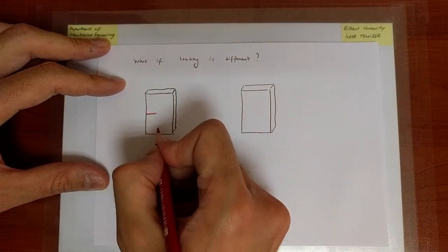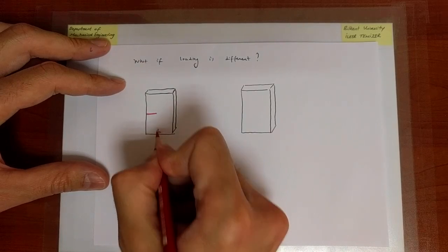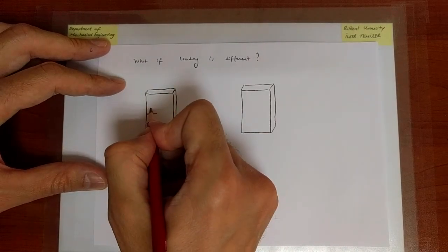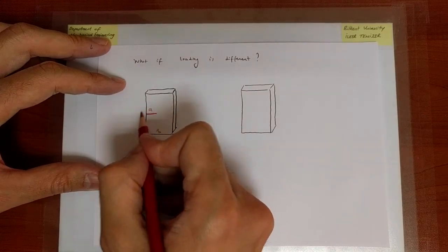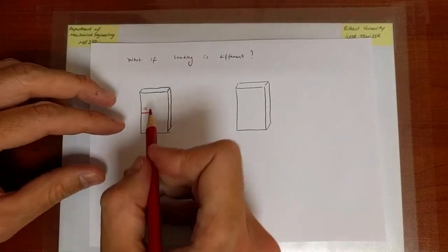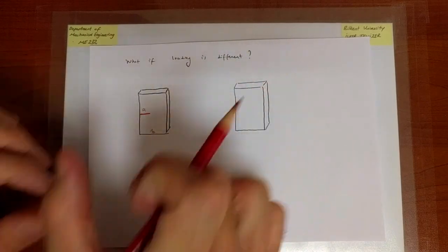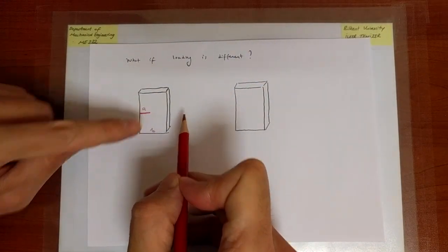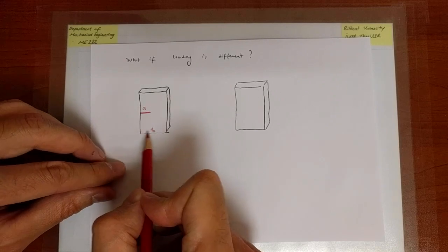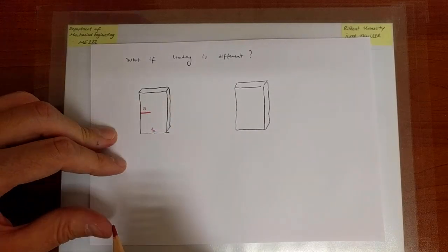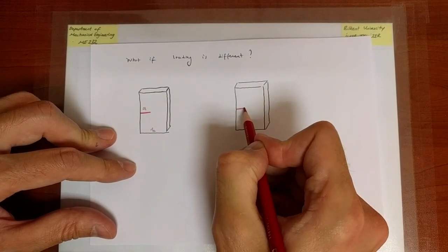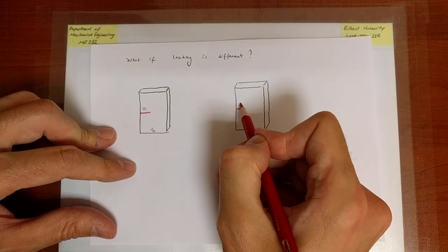Okay, so the definition of the width of the plate is B. The half width of the crack in this case, or the whole width, is A, but it's like half of an edge crack scenario, if you like, with two cracks. So when I split through the middle, the width is half, the crack width is also half. So that's the way we denote it.